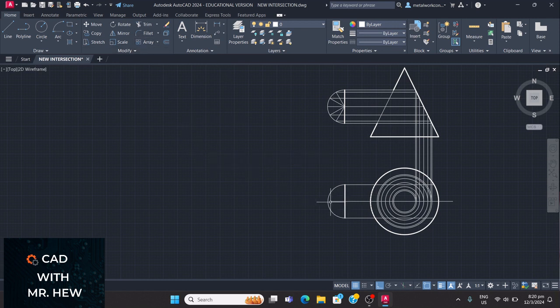And then now we're gonna extend this line. It's short, want to intersect here, right? So we can go extend. I'll click this line and it will be extended. All right. So what we're gonna do now, we're gonna draw a line from here, going up. I think 62 is the length, and the angle is 120. Right, enter.